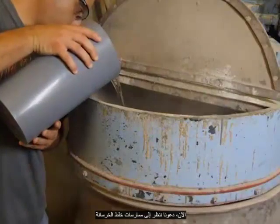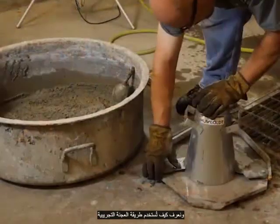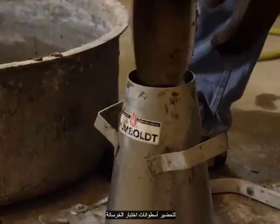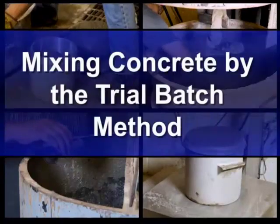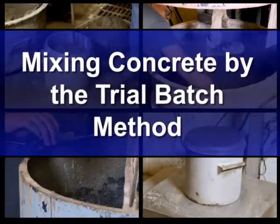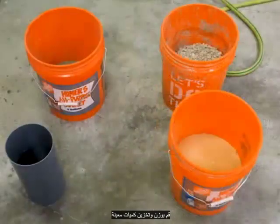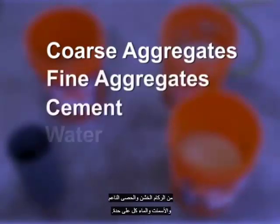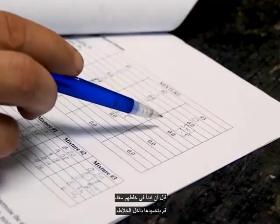A poor mix will crumble, segregate, and fall apart. Now, let's look at the concrete mixing practices in a laboratory environment and learn how the trial batch method is used to prepare concrete test cylinders for subsequent applications. Weigh out and separately store the given quantities of coarse aggregates, fine aggregates, cement, and water. Record the exact weights on the datasheet.